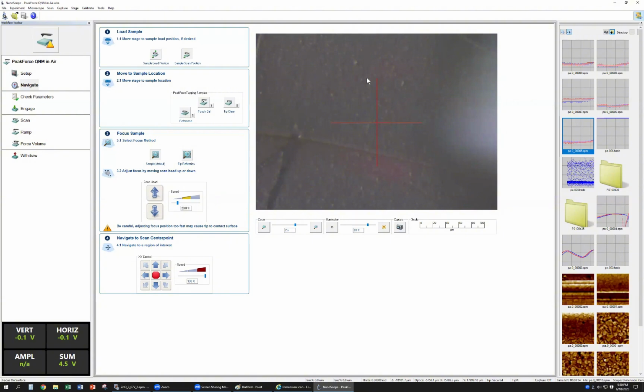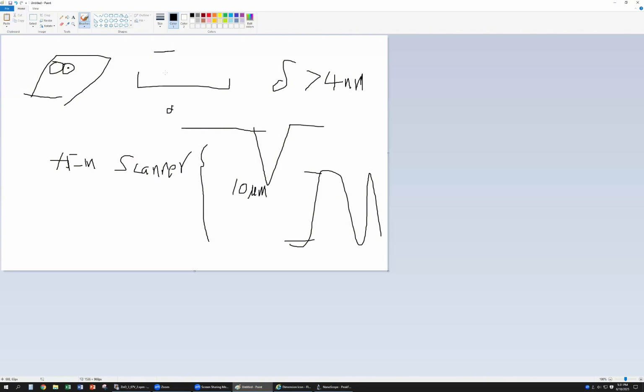Is this measurement related to the structure or to the material? If I change the structure with the same material, will the values differ a lot? Probably not. The Young's modulus is only related to the material, not the shape. Stiffness is related to L and W, the geometry, but the Young's modulus is already separated from the stiffness.